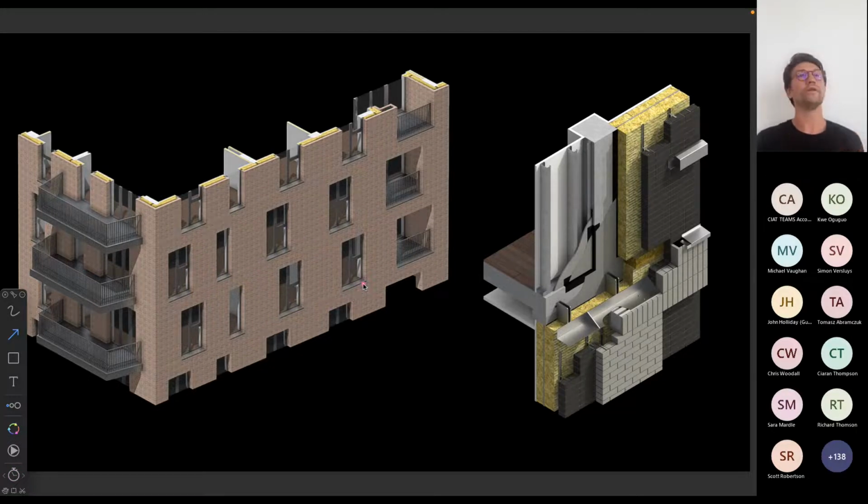If you're looking at a building and the windows are not one underneath another, they are staggered, then locating masonry support and having different precast elements here would be, A, not cost effective, and B, that would create some challenges with fire compartmentation, because you need to maintain within one compartment forming element here, which is a slab. You need to fit in that area the masonry support and the cavity closer.